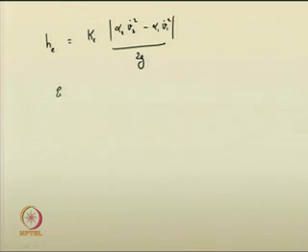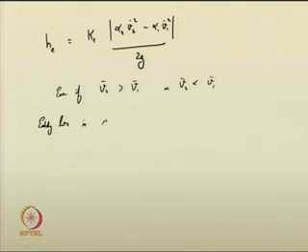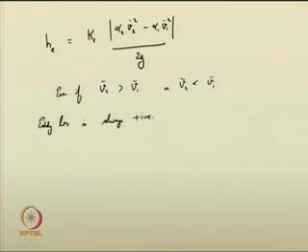So, whether V2 is greater than V1 or V2 is less than V1, your eddy loss is positive. There will always be eddy loss from upstream to downstream, whichever flow direction is there. Based on that, the eddy loss will always be positive, meaning it will be a loss of energy. You will not gain any energy due to those phenomena. So, eddy loss is always positive, you have to note it. It is the magnitude of the difference that you are going to take.